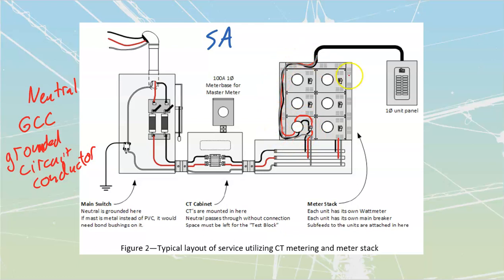But we see that all power that goes out to the actual unit, inside of the units that you're going to have inside of your duplex or triplex, quadplex, whatever it's going to be, are all going to be metered inside of there. So everybody that is in there is going to get their own meter. Now, they all get read in one central location, our metering closet, so that you don't have the hydro meter readers coming into everybody's individual unit.